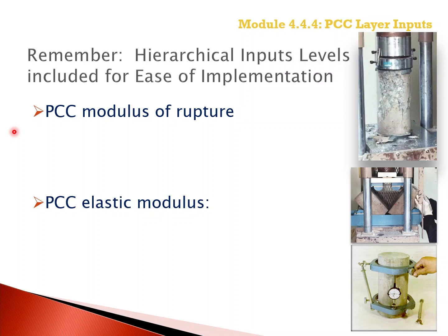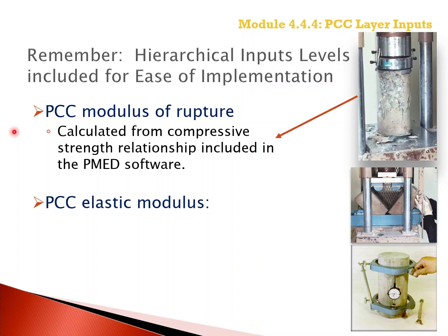The modulus of rupture can be calculated from the compressive strength using the regression equation in the PMED software, or it can be measured in the laboratory at different ages.